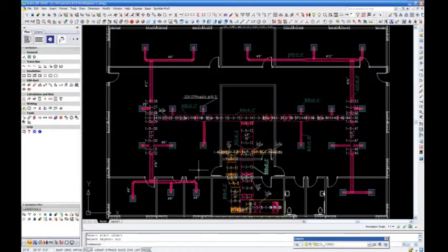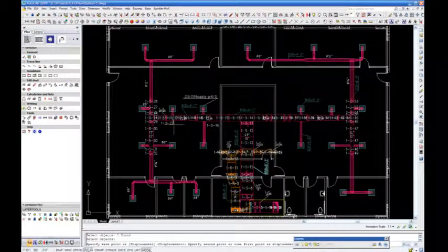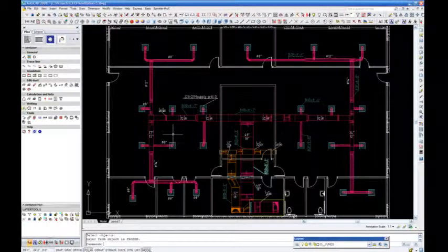We will repeat this on the supply air system. The software finds 60 pieces. We will select S for supply, our start point, and assign. Now the item numbers can be relocated to a position that they are better readable on the drawing.